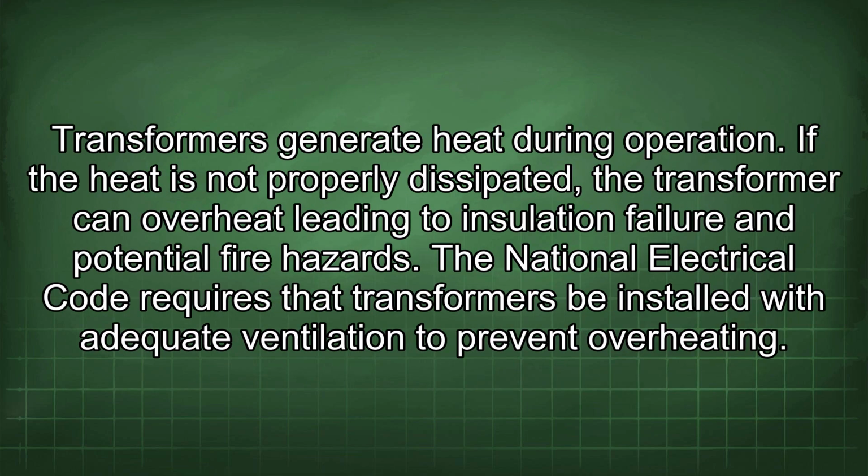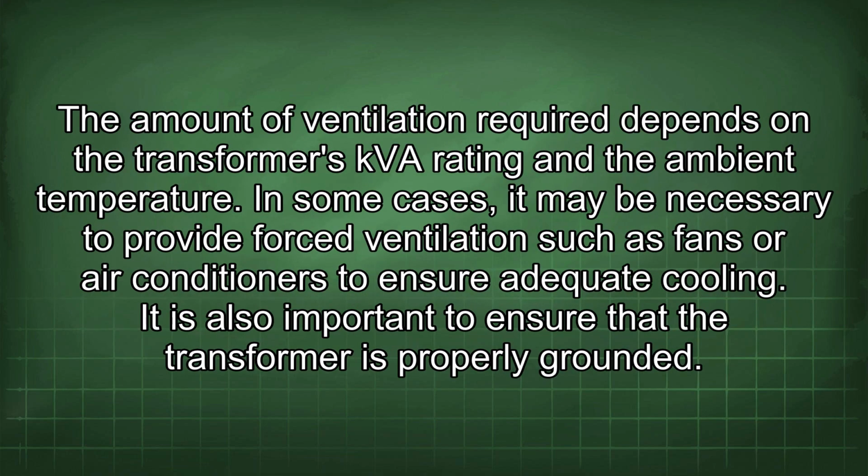Transformers generate heat during operation. If the heat is not properly dissipated, the transformer can overheat, leading to insulation failure and potential fire hazards. The National Electrical Code requires that transformers be installed with adequate ventilation to prevent overheating. The amount of ventilation required depends on the transformer's kVA rating and the ambient temperature. In some cases, it may be necessary to provide forced ventilation such as fans or air conditioners to ensure adequate cooling.